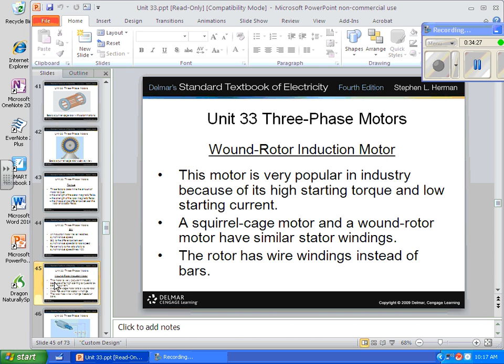So if you found a motor and you energized it and it turned and you had a, what do they call it? Stroboscopic thing so that you could find the speed of the rotating motor. And you found that it was actually turning at about 3,500 RPM. Number 1, you know it's a 2-pole motor. Number 2, you can see how much slip it's got, right? Just from hooking it up and running it. Oh, what a good thing to know, right?